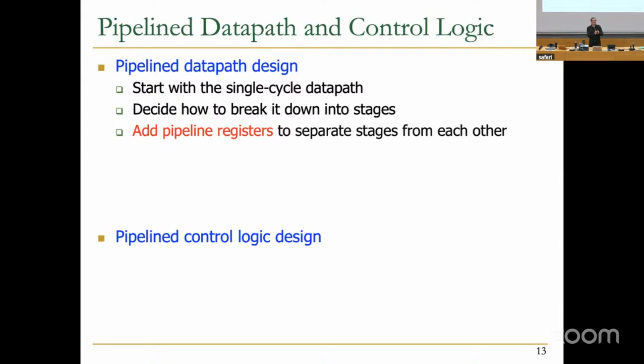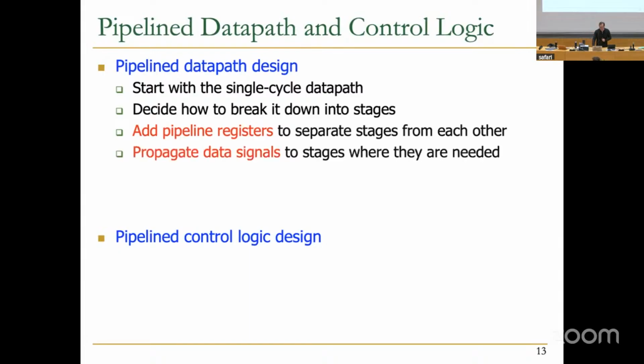Our goal is to basically keep processing instructions, keep moving instructions from stage to stage. And every cycle you do something in each stage. At the end of the clock cycle, you finish what you're done, latch it at the pipeline register at the end of the stage, and the next cycle will start with what you have latched in the previous cycle to the register. Okay, so that's the purpose of the pipeline registers. I'm going to show you this again pictorially.